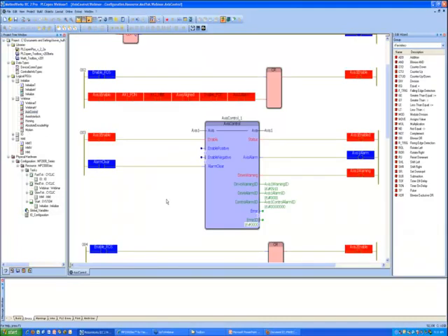So it's basically just taking 3 of the PLC Open function blocks, MC Power, MC Read Access Error, and MC Reset, combined into one. So at the very least, it's saving some code space in your project and also some debugging of additional ladder to kind of incorporate all those features. And there you have it. One function block can handle those 3 things.